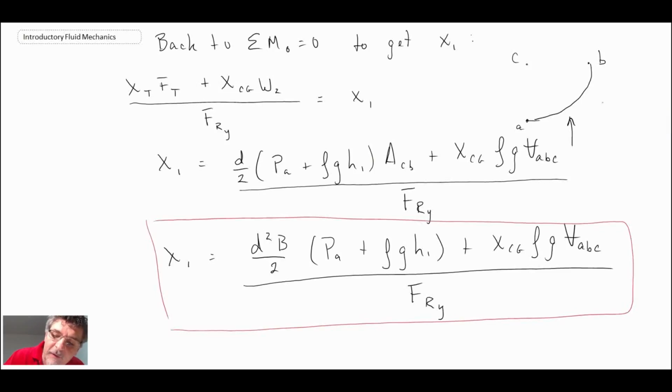And what we did is we solved for these forces here, which we had Frx and Fry. But what we were doing now is trying to figure out where they act, and what we did is we defined y1 as being this direction, and then x1 as being in this direction, both from this origin. So the force acting could be something like that, and then it would be like that on the surface. And that would then give us, so the center of pressure is not exactly right on the surface as we get from this analysis, but it's an equivalent force, and consequently it gives us an indication as to where the center of pressure would act if you went through and did the full complete complex integration that we looked at the beginning of this segment.